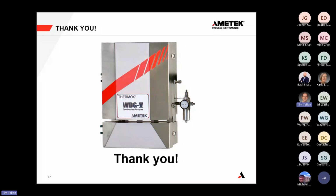So the latest question that I see here in the chat is, what's the difference between a high particulate HP analyzer and a blowback analyzer? The difference is actually all the practical things that you could think about. A blowback analyzer is designed well for dusty applications that have dusty particulate, not sticky particulate.